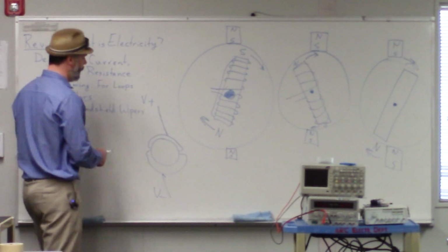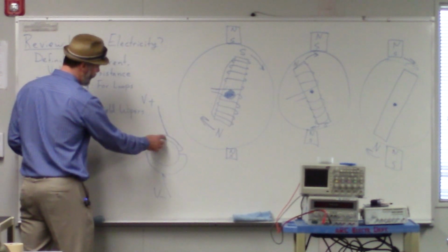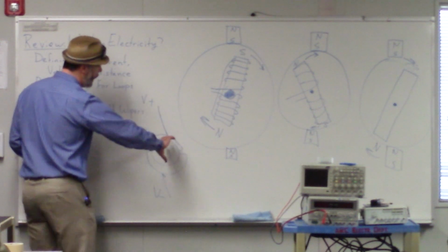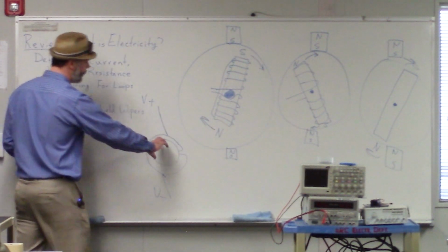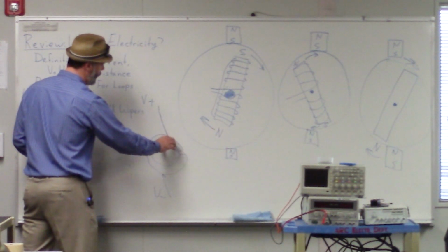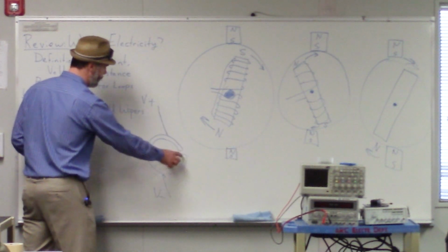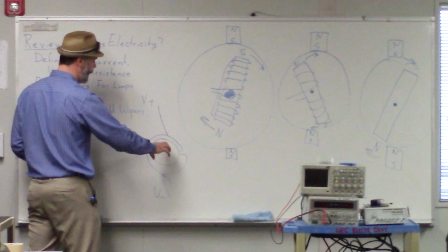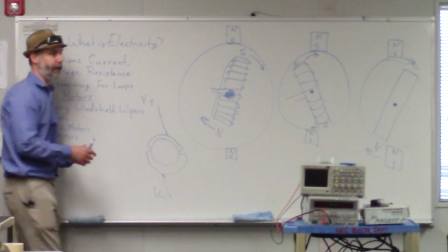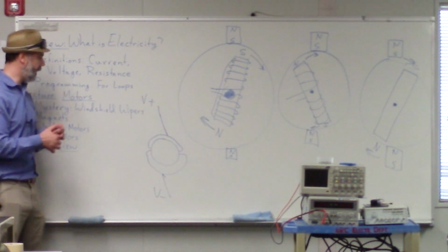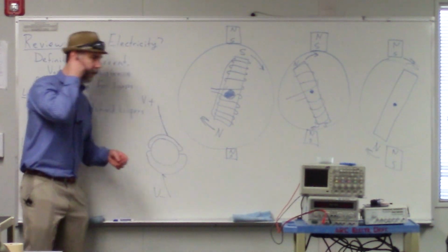So what happens is that this positive voltage is touching this connection, and the negative voltage is touching this connection. And then as the shaft turns around, at some point the little electrical connections on the shaft are going to rotate so that now the negative voltage is connected to this one up here, the positive voltage is connected down there, and that's how the polarity is changed. So it's all done mechanically, okay?